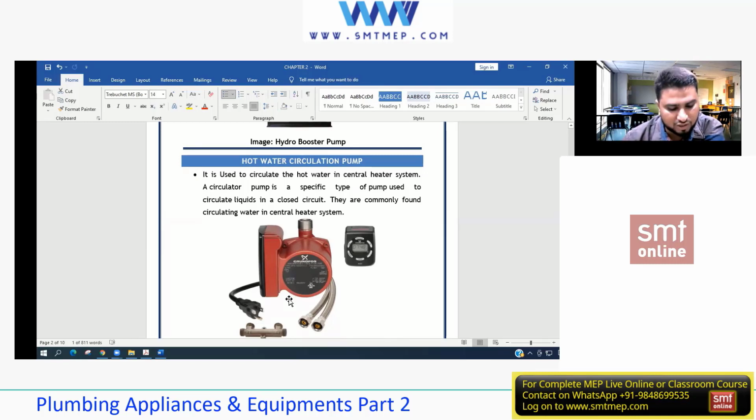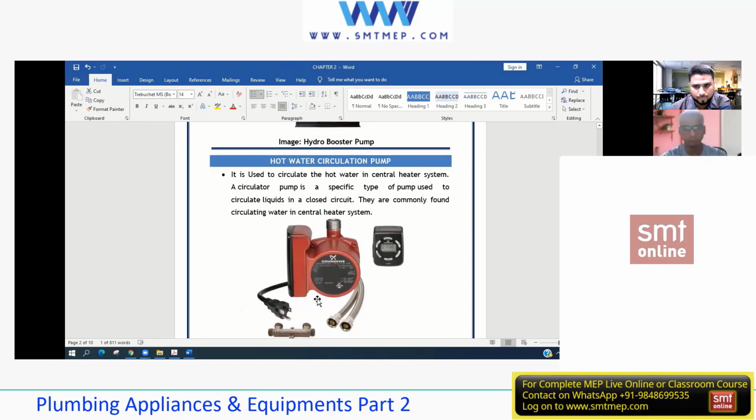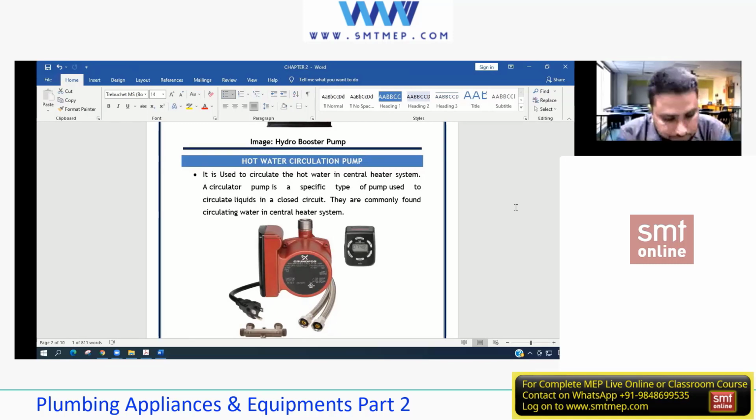Excuse me, sir. Yes, please. Sir, I have one question. For example, if a building has 8 floors and the municipal water can provide only for the 4 floors, the municipal water pressure is not enough for the rest. What we did, we installed one transfer pump, which provides water to the roof water tank, and then we install a hydro booster pump to maintain pressurized water for the top 3 floors.